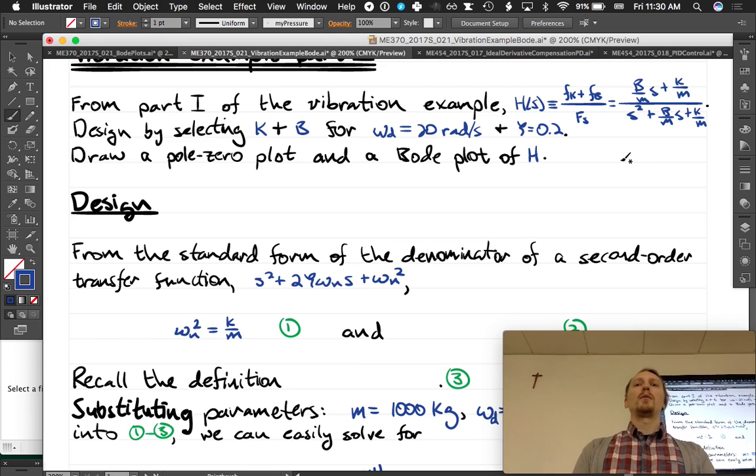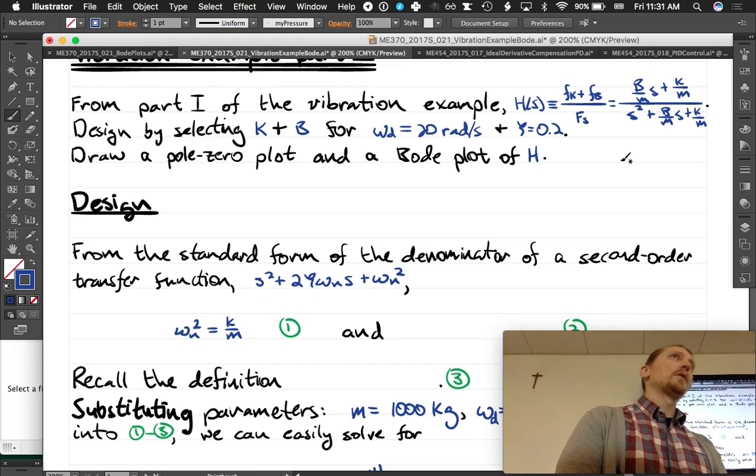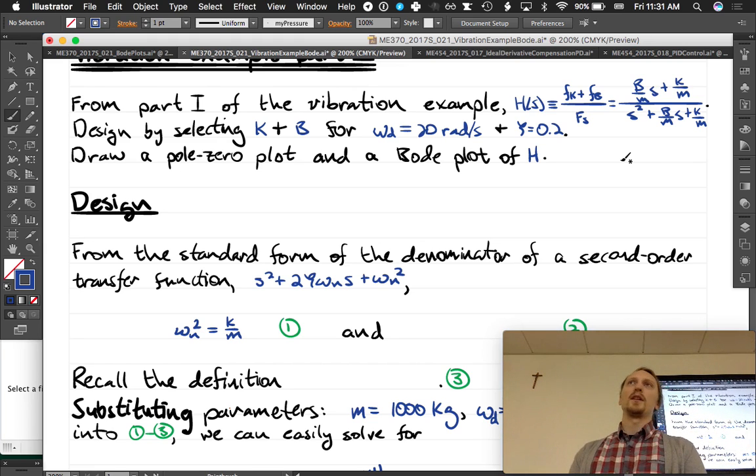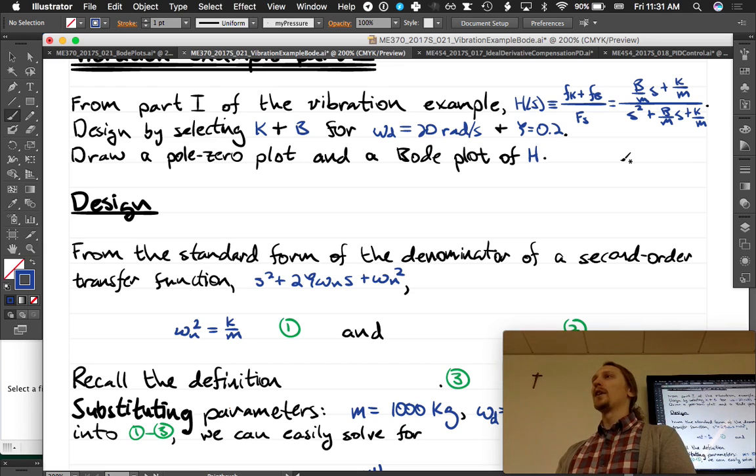So when we are talking about the transient response of these systems, what typically dominates the transient response are the poles, the denominator. Remember that poles are equivalent to the eigenvalues, which are equivalent to the roots of the characteristic equation, and these things sort of dominate the dynamics.